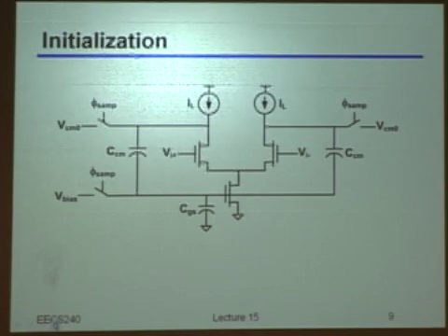Okay, so this is, I was saying, a really brute force approach to basically initializing your amplifier at your common mode. So the idea here is I can exploit the fact that normally in a switched capacitor circuit, I always have one phase in which I'm not using directly the amplifier, right? So I can call that phase, in this case, the phi samp. And I can use the amplifier maybe to fix the common mode problem just right at that time in which I'm not using it for different purposes. So once again, I will have some bias circuit here, just to make it clear as in the previous slide with some resistor or whatever, and a plug in there.